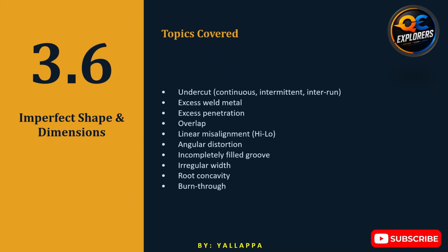This group demonstrates why a welding inspector needs suitable measuring tools and gauges. A weld should not be accepted simply because it looks good. Where an acceptance limit is specified, measure the condition and compare the result with the governing requirement. We will begin with undercut, one of the most common imperfections encountered during visual inspection.